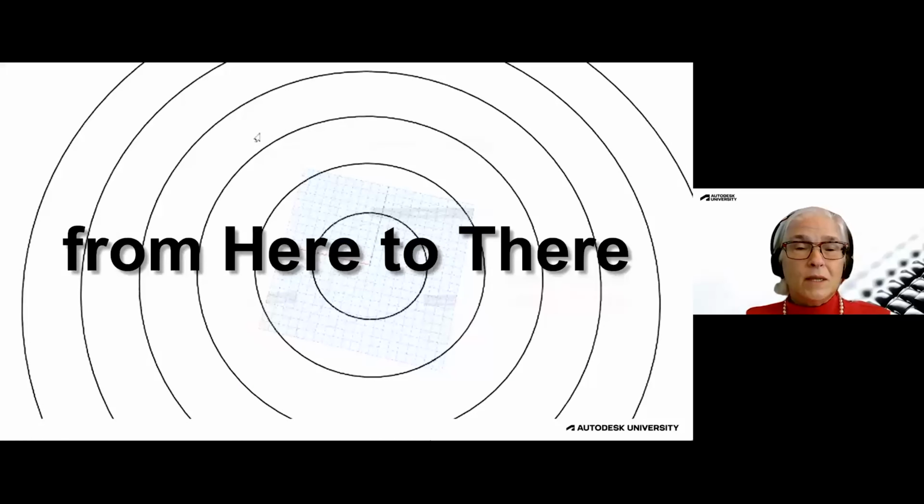One of the things that happens in programming with Dynamo is that distances are straight lines. Well, not really straight lines, they're considered curves. They are not paths of travel. For buildings with doors, this would yield a false sense of nearness. It's a level of complexity for which we didn't have time in the development of the graph to date. It would be a potential enhancement that I, being an architect, would like to see.